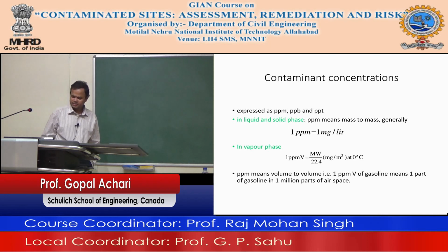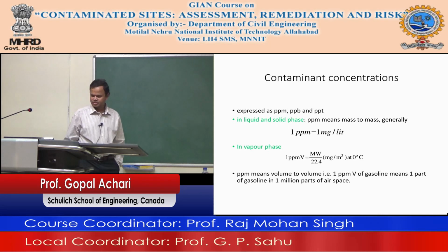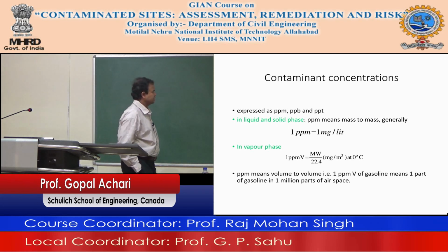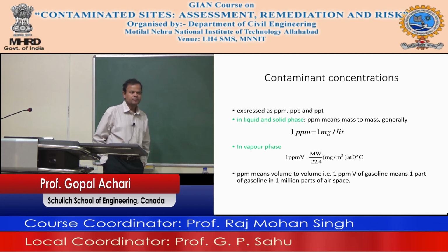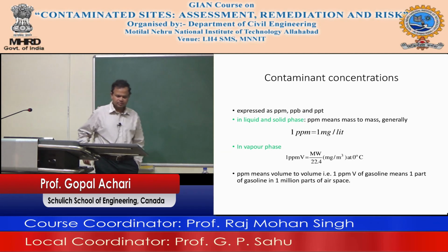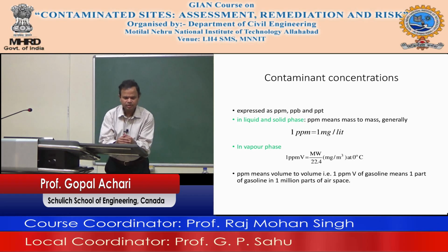So what about designing a remedial system? First, you have to do contaminant delineation. This is the site characterization I talked to you about yesterday. You have to determine the site geology and hydrogeology. This is a time when, if you are not a geologist or a hydrogeologist but you have a site to clean up, it's not a bad idea to bring in a geologist or a hydrogeologist to talk about the site.